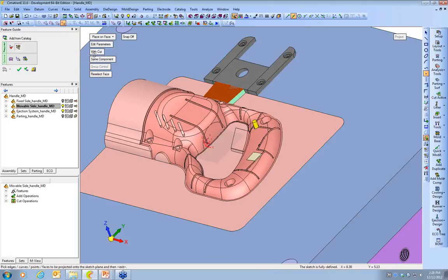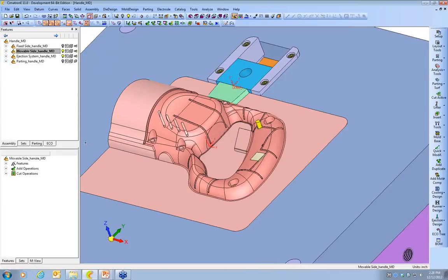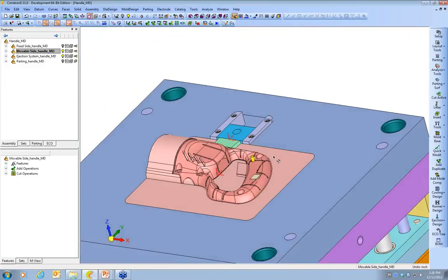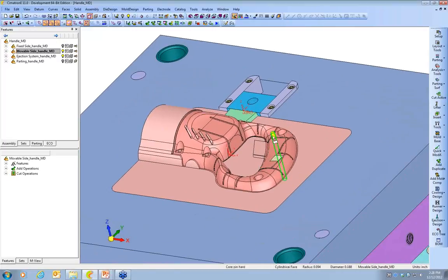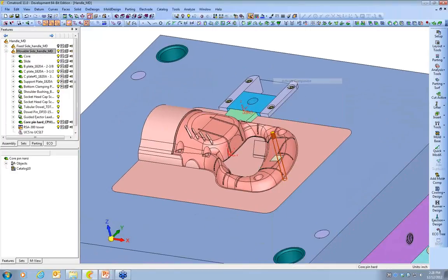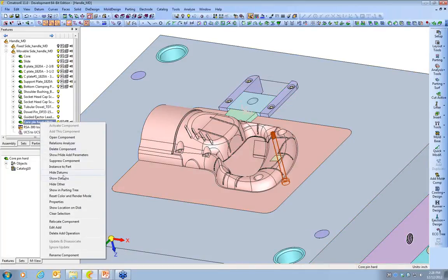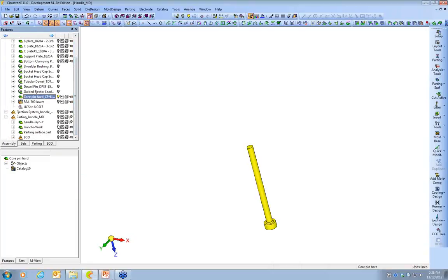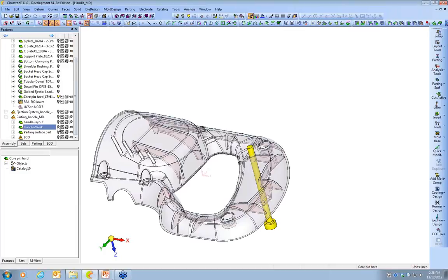And we've got a parameter here with cut. So that's going to create all the pockets and the screw holes. They come right from the cavities. And of course they follow along as the parts may move later on too. While I was working on this core pin, that actually still needs some shape to be complete. It's actually pretty easy work in Cimatron because we always reference right back to the work file that holds our part data. And we have cutting functions that are specifically made just for cavities, for lifters, for inserts like this.